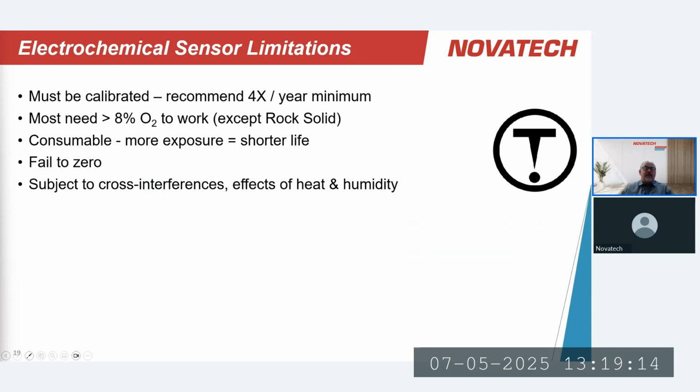They have a finite life. As I mentioned earlier, that reaction that is occurring means that the sensor is degrading over time, and we calibrate to compensate, but eventually you get to the point where you can no longer compensate for it. The sensor has to be replaced with a new one.